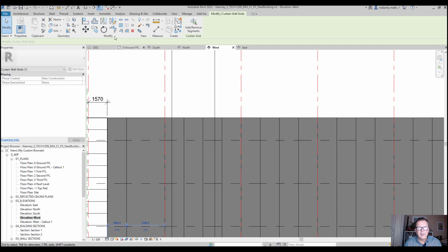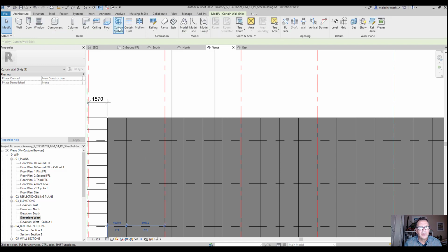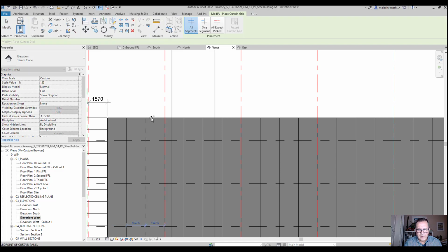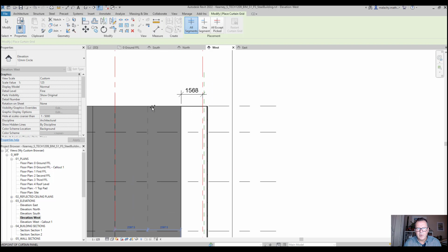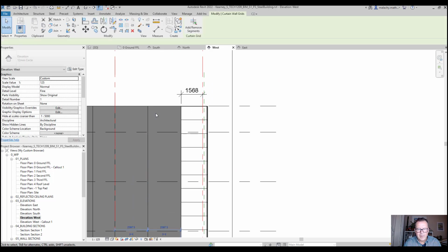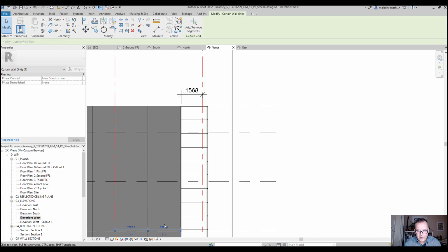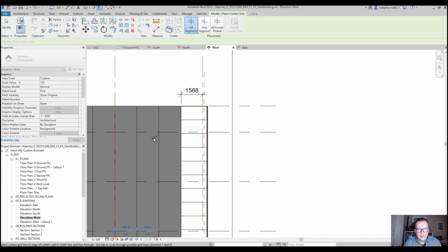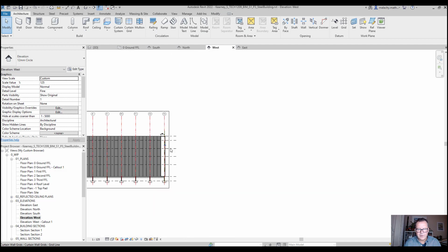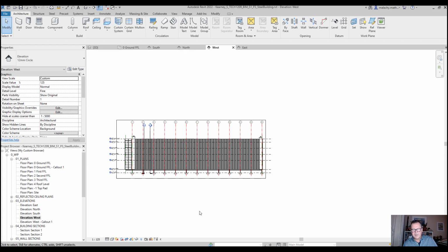All right, now I'll go in, I'll put another curtain mullion in here in between the two. Look, that's 2.5 mil out, so that's fine. And then I'll do the same over here. I'll just place a grid line. Now remember, it's the grid line that we're moving here. There's the timber dimension, 1600. Okay, and then we will place in between. Now, so we've got a nice even structure all the way across there.